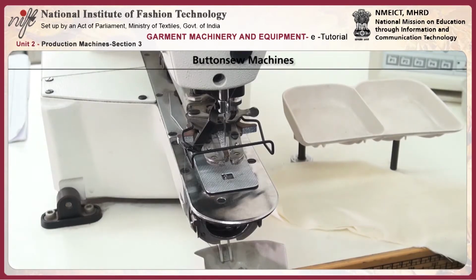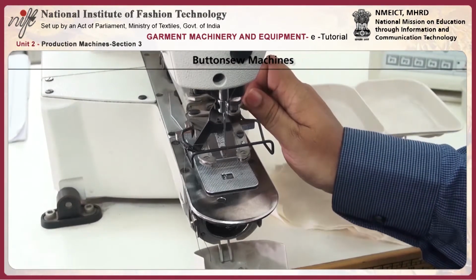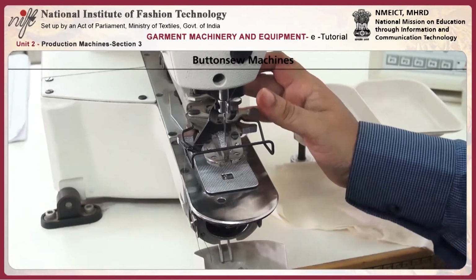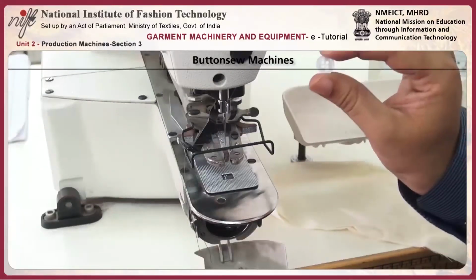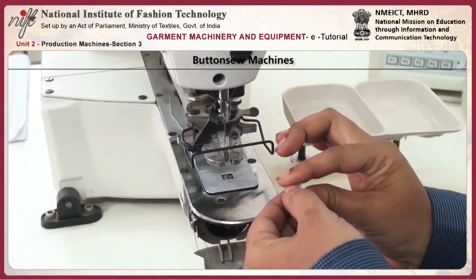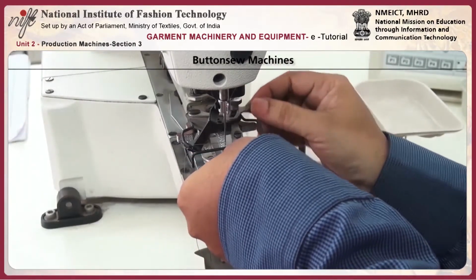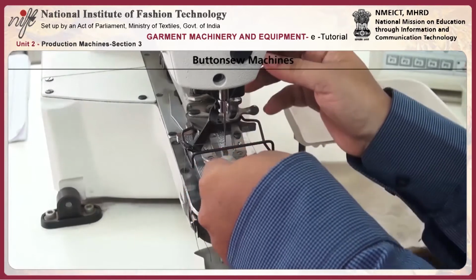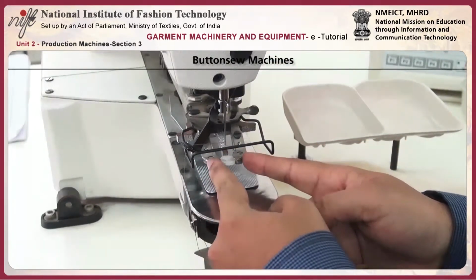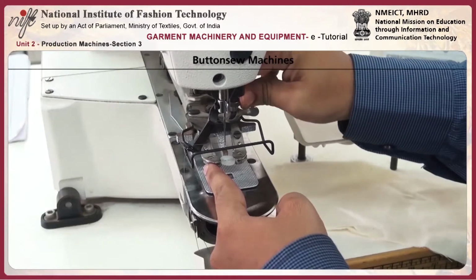This is a button sew machine based on lock stitch type. You can see a clamp here which can be adjusted by loosening the screw and pressing this lever for the diameter of the button that is to be sewn. Now we have a 4-hole button here which I am going to insert and set the clamp width. Now you see that the clamp is holding the button firmly. Now I am tightening the screw to fix the clamp width.